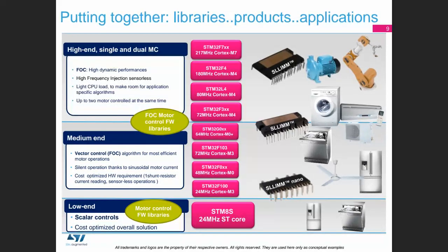If you develop a scalar control application, it's very easy. You will set the voltage and frequency. In scalar control, we want to control the voltage over frequency ratio. For example, you will send 200 volts and at this application you will send half of the frequency. It means V by F control.